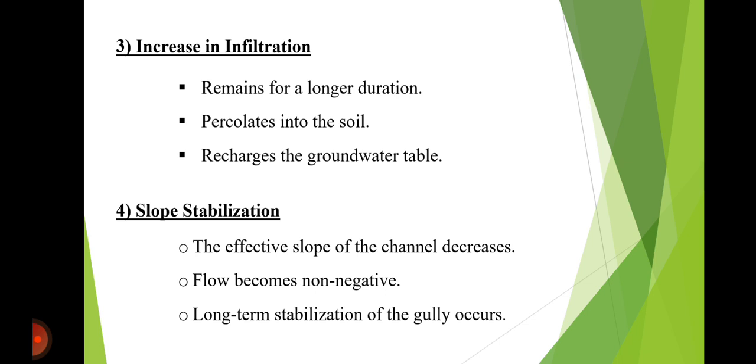So when we write the flow sequence, first of all we write rainfall. When there is rainfall, there may be runoff. When there is runoff, the check dams reduce the velocity, then temporary water storage, next sediment deposition, and then infiltration, and then safe overflow, next gully stabilization.